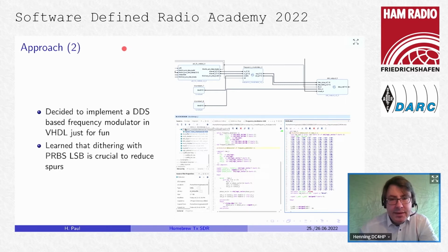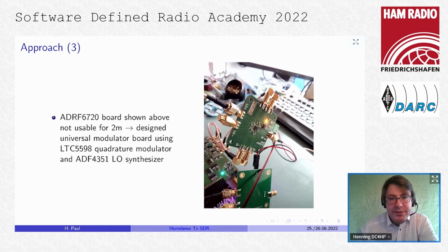It means from 2.5 megasamples input, you can get 40 megasamples output. This also has one nice advantage: for shortwave transmission, this is essentially important, you can do a frequency up-conversion in the digital domain. I will come to that in a moment.